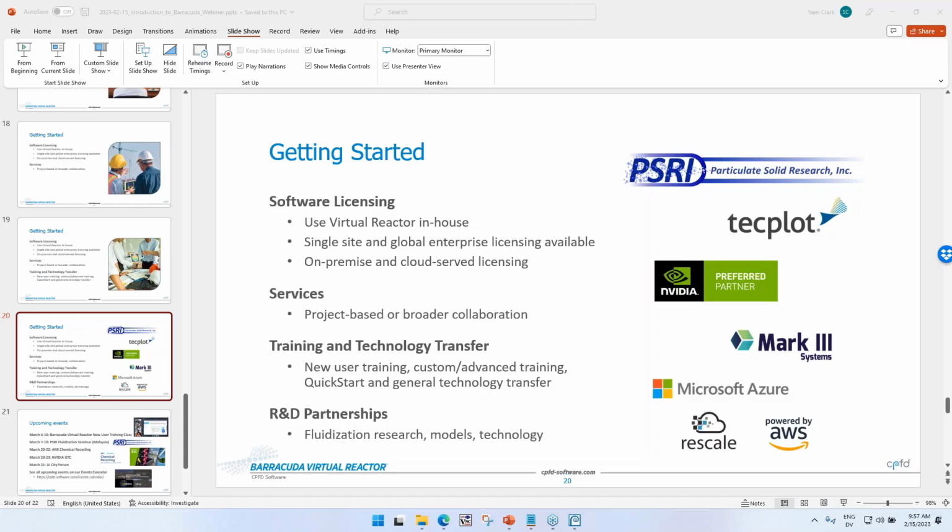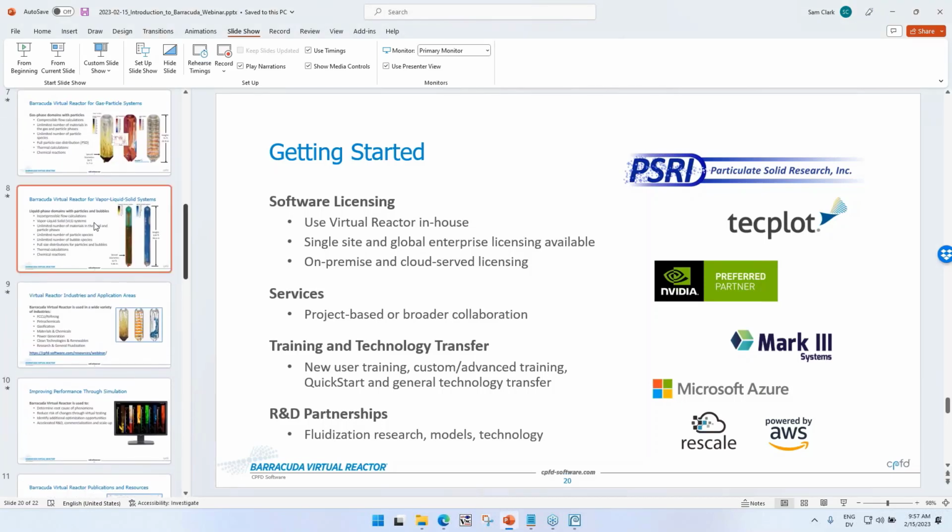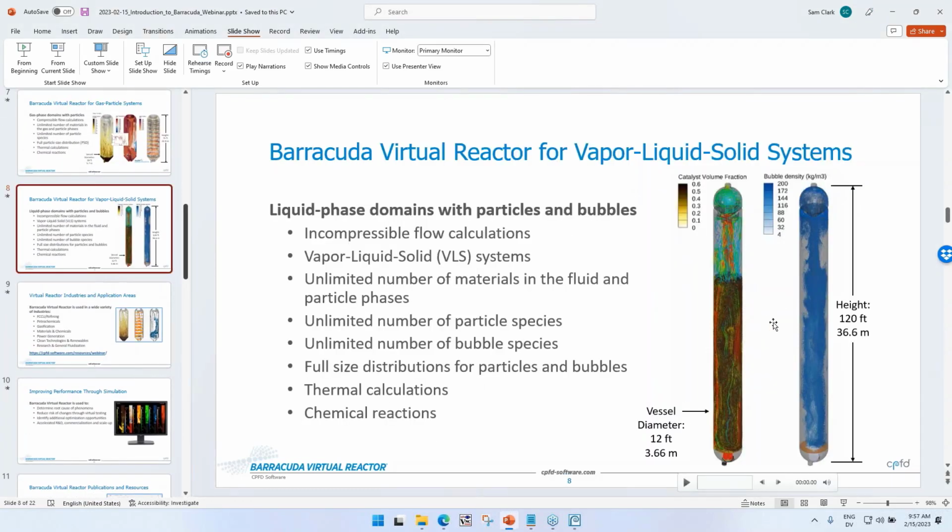And how about slurry bubble systems? Can they be analyzed? Is it a Eulerian-Lagrangian approach or Eulerian-Eulerian approach? And can we model bubble coalescence and breakup? Sorry, that's a couple of questions. Yeah, no problem, they're all kind of together. The slurry flow, if I understand correctly, could be something pretty similar to this ebullated bed system.